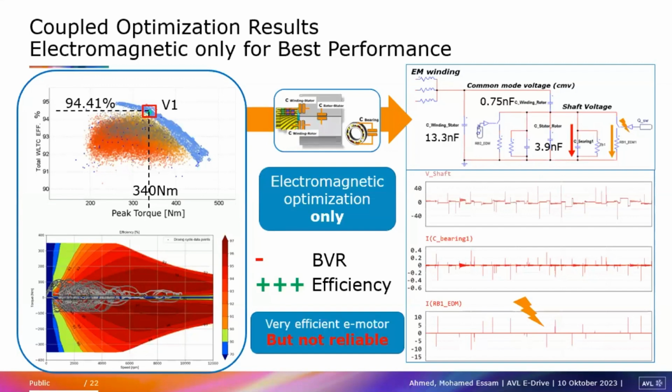Yes, there is what we call the asymmetric flux linkage that can happen through the housing. It happens through the bearings, happens through the shaft. This is basically, yeah, sort of leakage flux, actually, which induces inductive bearing currents. Here it was not included in this study.